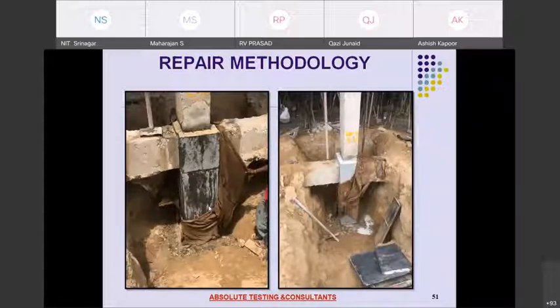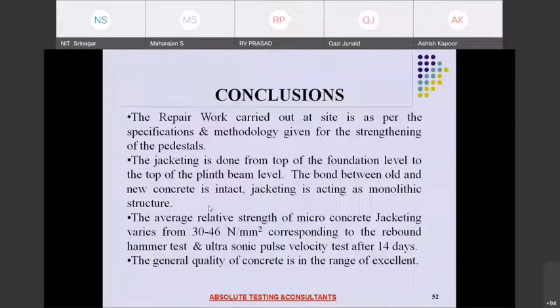Now here is the challenge: how can you ascertain that this concrete is filled completely in that area? Here again non-destructive testing was done. What we have to do is place one probe on the upper face of your structure and the other probe on the other side, and we will find out the values of wave propagation, whether it comes under the range of the required grade or not. So here we were getting the repair.